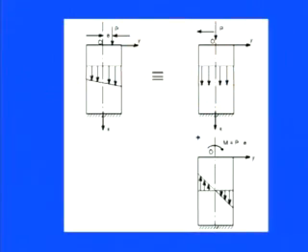In this diagram we have the structure, which extends along the x direction. This is the rigid part, and this particular center line is the centroid. So instead of keeping the load at the centroid, if it is displaced by e, as I told you, it can be replaced by two main things. One is the load itself, so we shift the load P to this particular center point. This is the center point here.